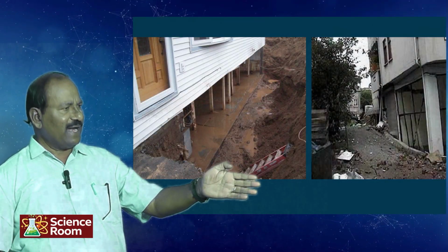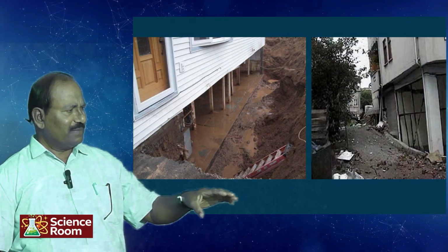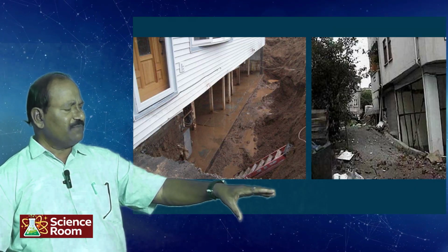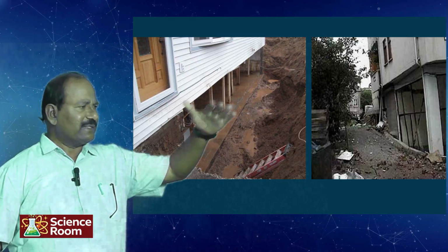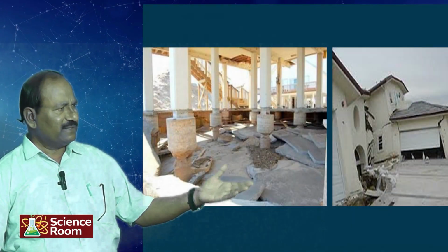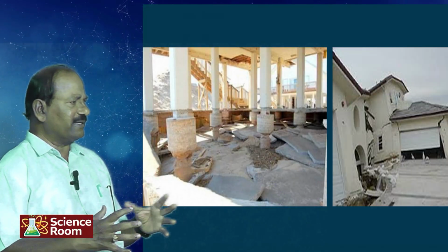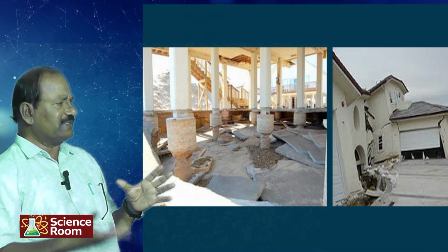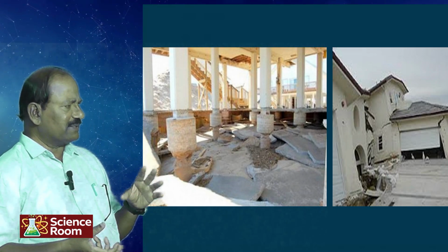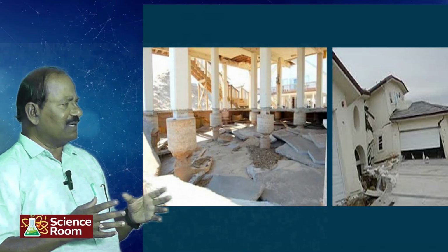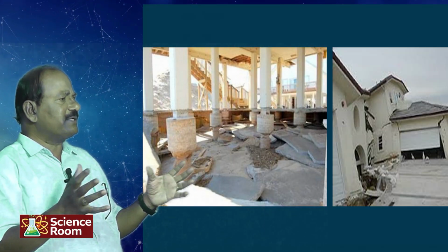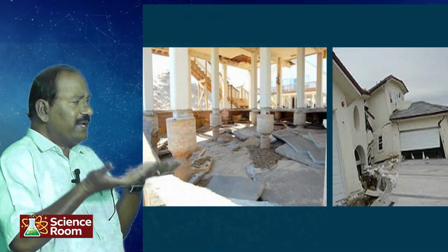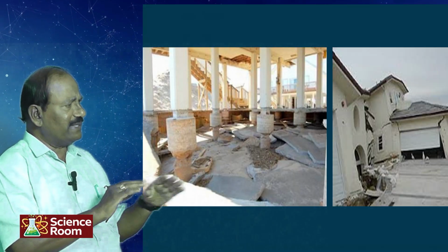Next, in the wetland, the pile foundations are there. The piles are affected by the chlorides and sulfates, the reinforcement is snapped, and then the building is totally toppled. Here you can see the same thing. Here the sulfates are reacting with the cement component, the calcium aluminates. The sulfates react with the calcium aluminates and are converted into calcium sulfoaluminates, which is an expansive type. Therefore, the bottom floor is being heaped up, and the flooring is completely deteriorated.